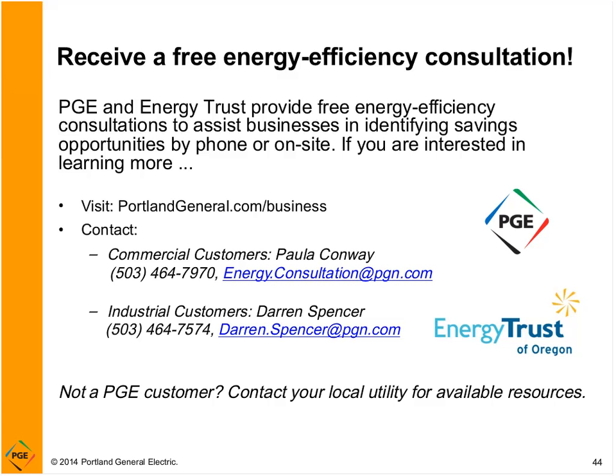But now you can get lamps that last almost as long as the ballast itself. Some of the ballasts should last at least 50,000 hours, some even maybe up to 75,000 hours. But if you have a really long life T8 lamp, by the time you need to replace the lamp, it might be a good time to replace the ballast as well. Or by then, it's probably going to be a good time to go to LED.